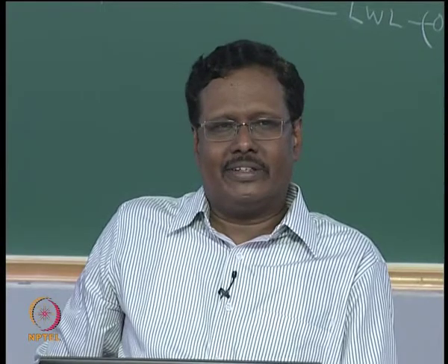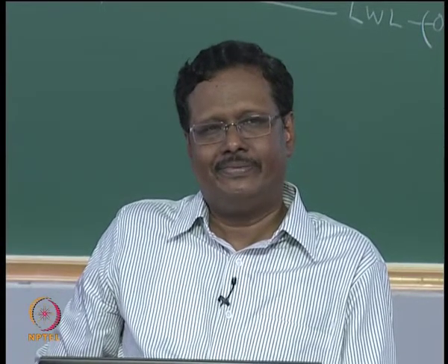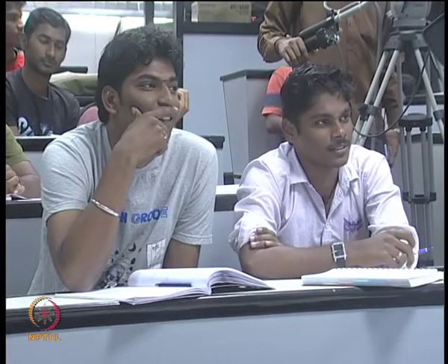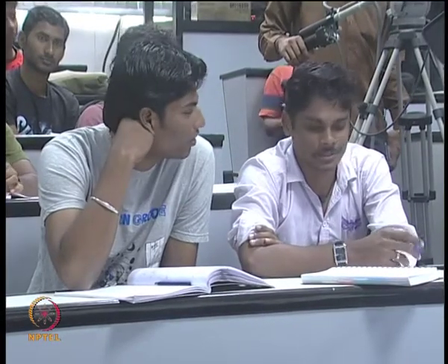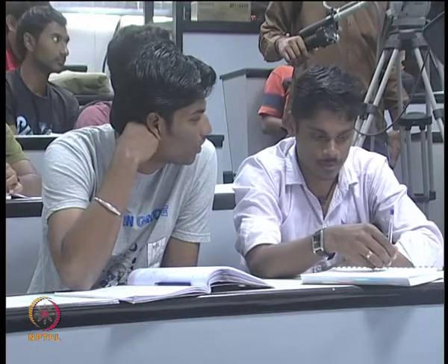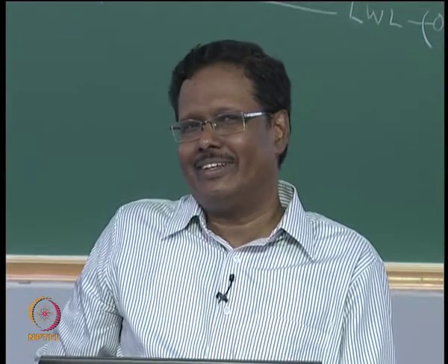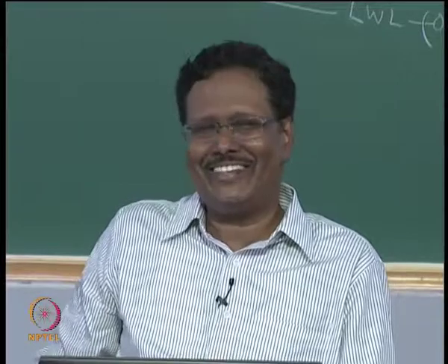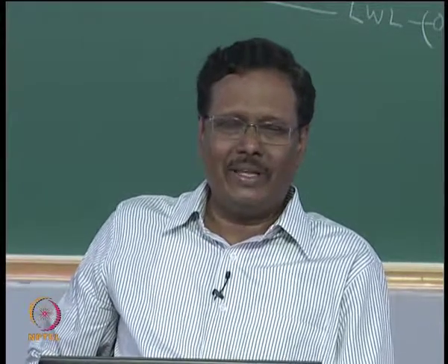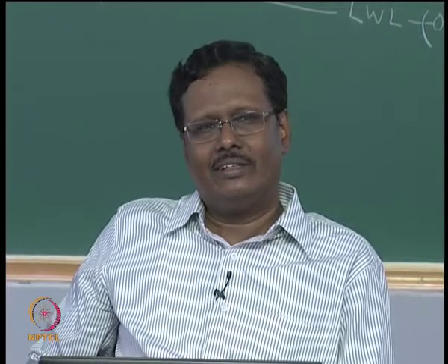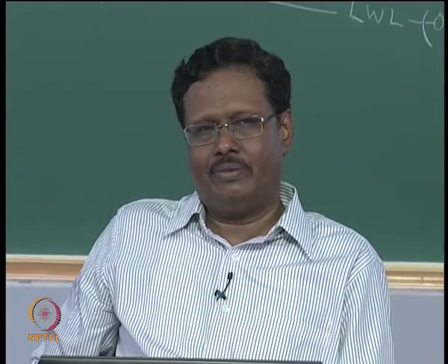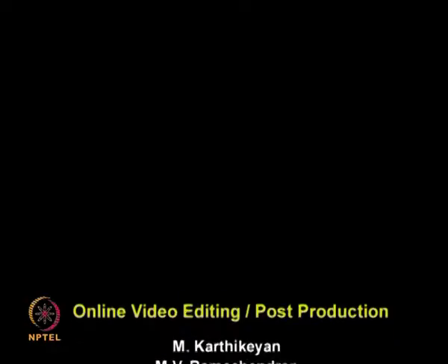What is the permissible deflection? It relates to the span. How much is it? Span by how much? Span by 300 is the wrong answer, but it is very close to the right answer. I think it is span by 350. Otherwise I will get confused if you tell all these values. Please check IS 456. No, IS 456 is only for concrete. Please check. Span by 350. What is the permissible crack width? 0.3 mm, but it is revised now. It varies from 0.1 to 0.3 mm.